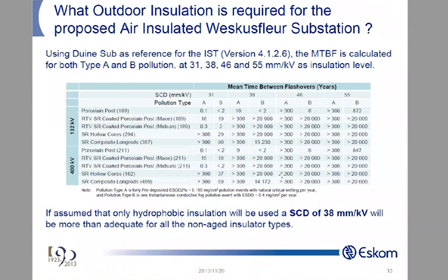But also what happens is that you normally have in your coating or in your insulator itself, alumina trihydrate. Alumina trihydrate is actually water molecules which can become available. Aluminium, okay, with OHs, and then when they break off, they become water molecules, and then the arc heat is transferred into the water molecule and it explodes, and as it explodes, it shifts the arc, and that's how you get arc resistancy, okay?